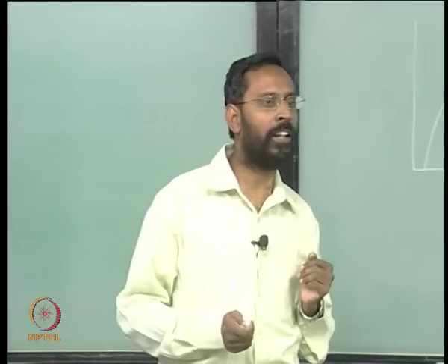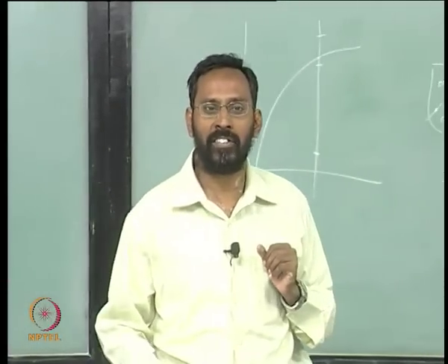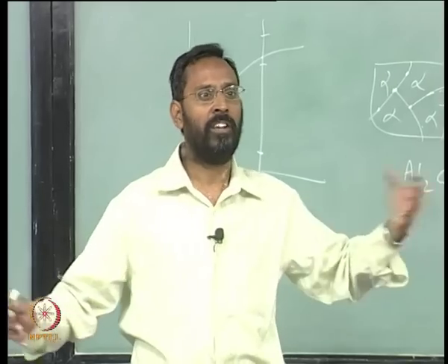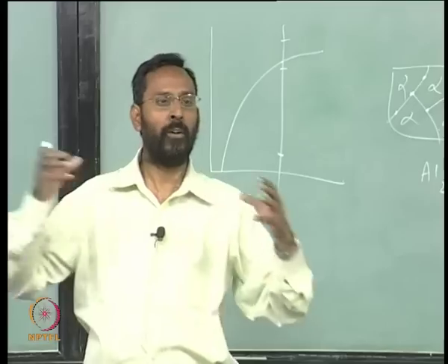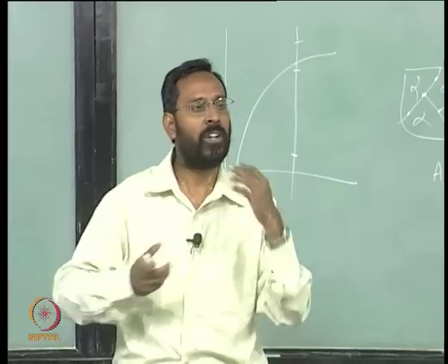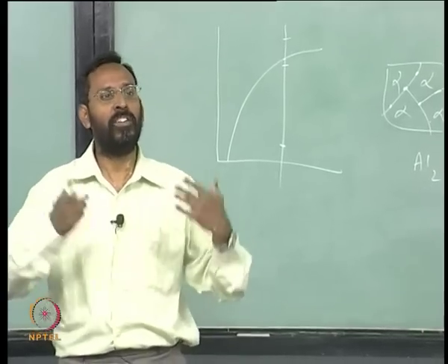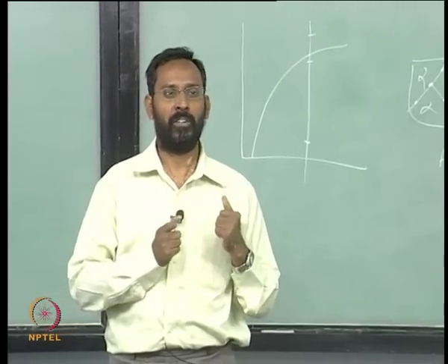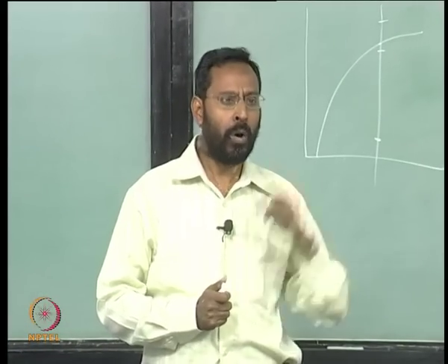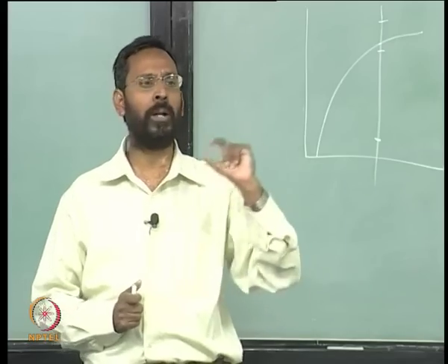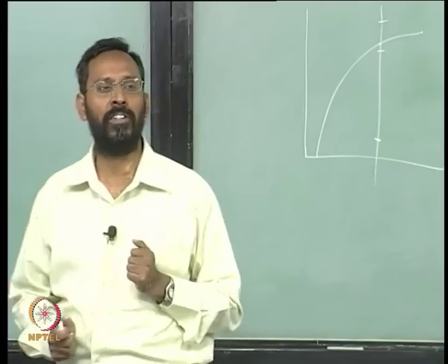Theta cannot nucleate within the grain because theta has a structure which is entirely different from that of the matrix structure, which is tetragonal, whereas the matrix is an FCC structure. Because theta cannot nucleate, the system starts looking for other transient phases which can nucleate within the grain. That is how you see the coherent phases come into the picture. Only when the second phase is coherent with the matrix can it nucleate within the grain. If it is not coherent with the matrix, it cannot nucleate within the grain.